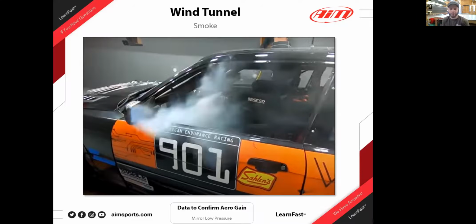But that would be, if you're in a class that allows you to have some sort of side window. Most do not, so everybody's in the same boat. It would get rid of all that turbulence and drag coming down the side of the car right there. And like you mentioned, the mirror, on my own car, I have a convex mirror up in the front, so I removed my passenger mirror and used one of those little convex circles with a cone going over it to essentially get rid of my mirrors, because they're a source of drag, and if you can get away with taking them off, again, a little bit, all add up.